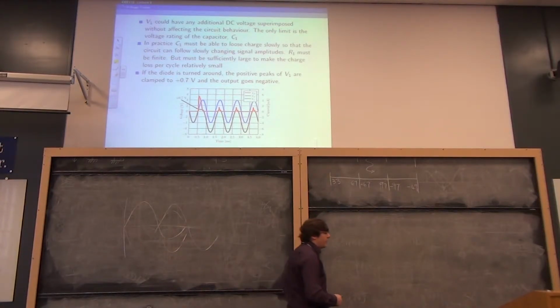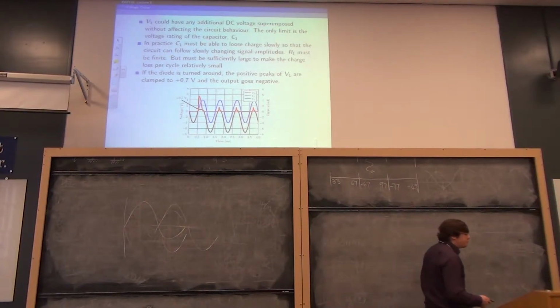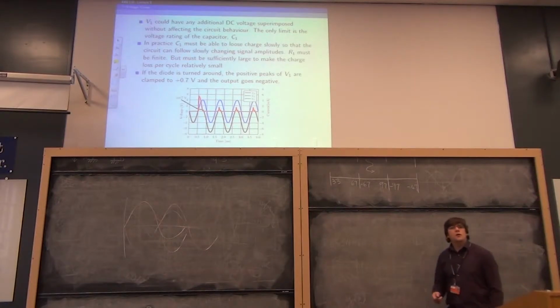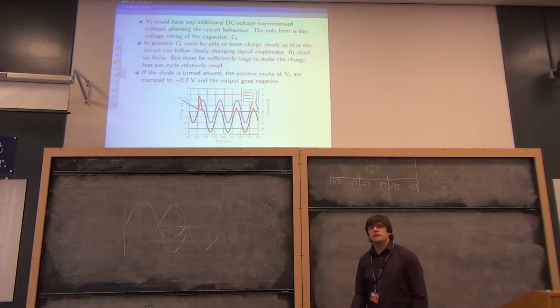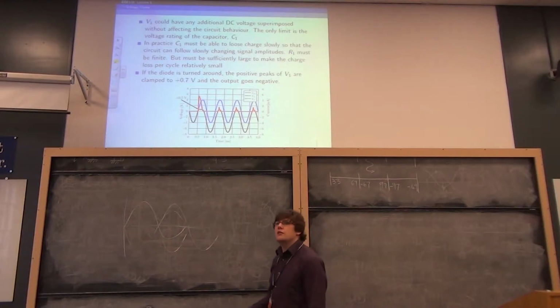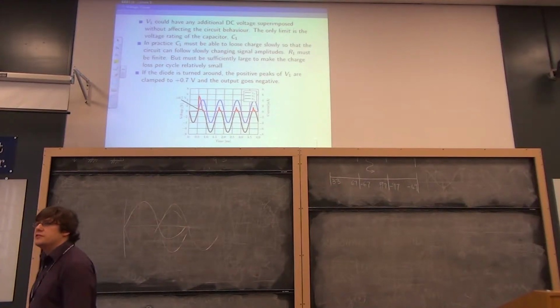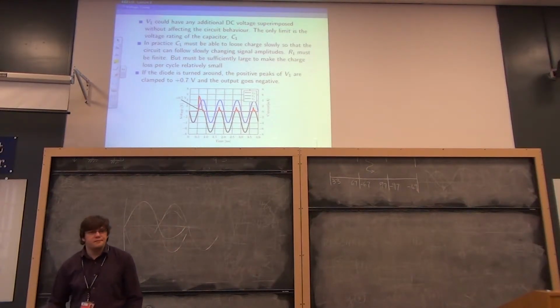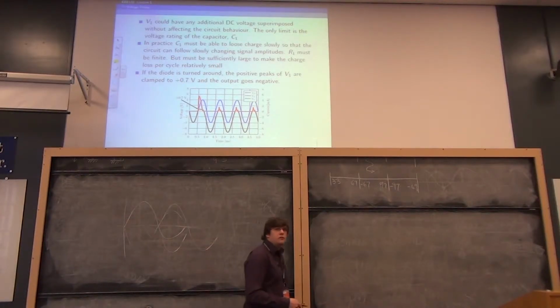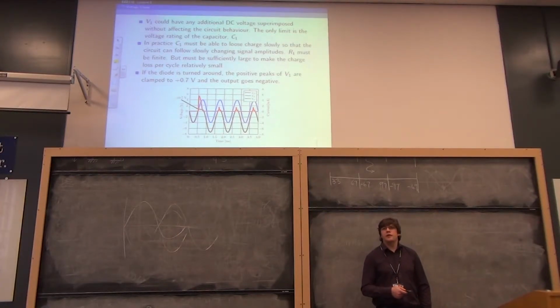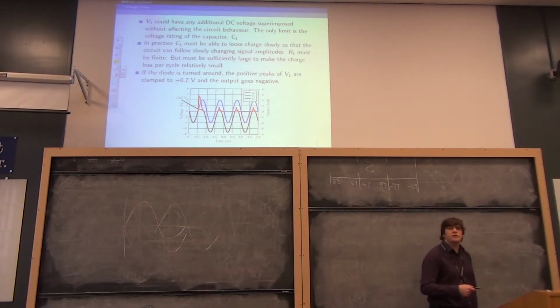In a real circuit, C1 has to be able to actually lose a bit of charge through R1. The reason is, if you've got a signal which has a DC value that you need to restore, but that DC value is not constant, it just varies quite slowly, you must be able to follow that changing DC value. So it's the difference between DC and constant. If you can't lose a bit of charge from C through R, once you've got C nice and charged up, you won't be able to discharge it to a lower value to follow that waveform, should you need to.